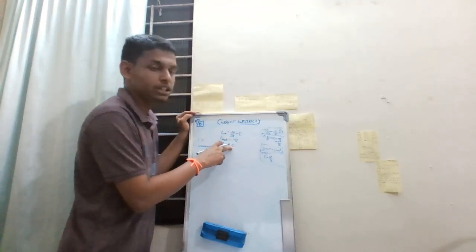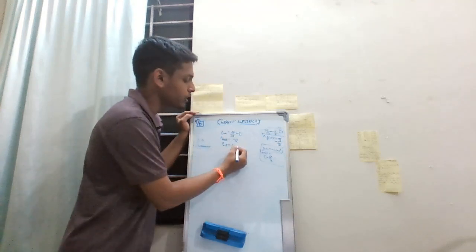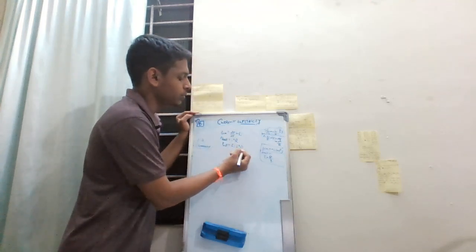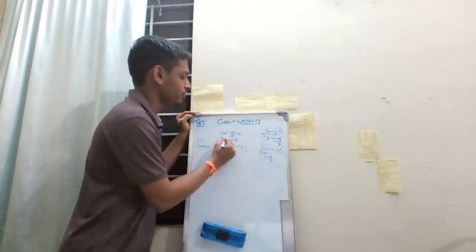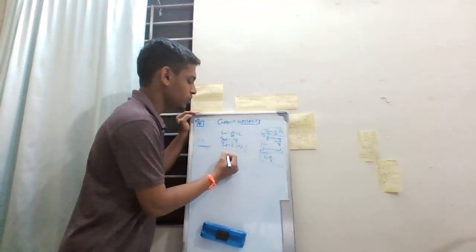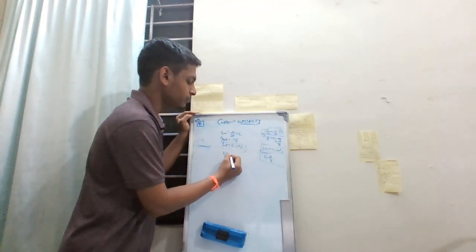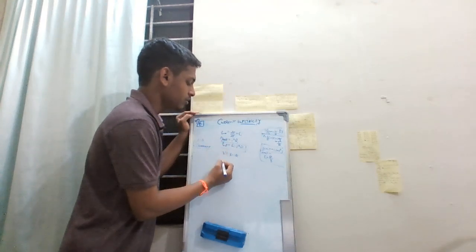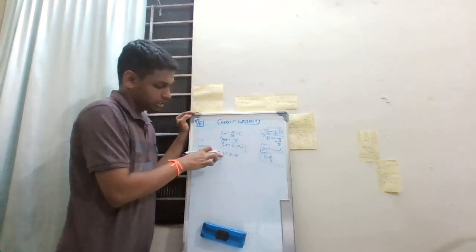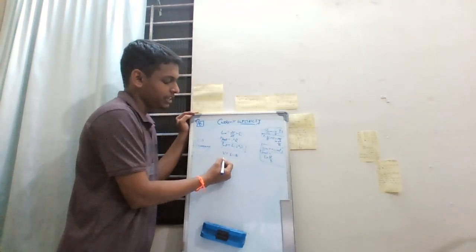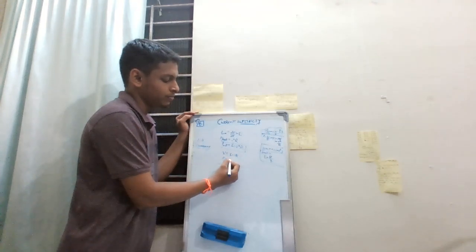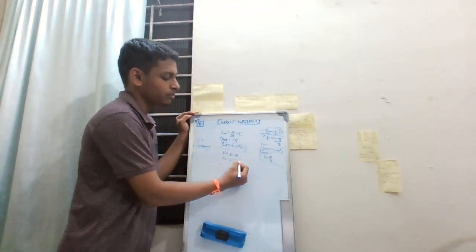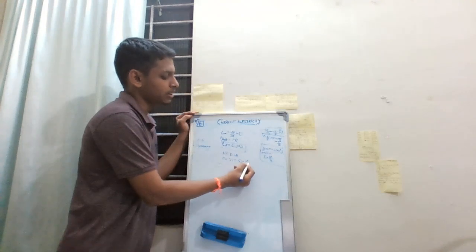Here we are writing EI because of electromotive force, and it loses this much energy. So the potential would be E minus IR, but if we consider this is V, so we know that power is V times I, so it would be EI minus I squared R.